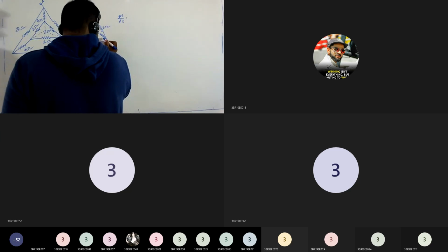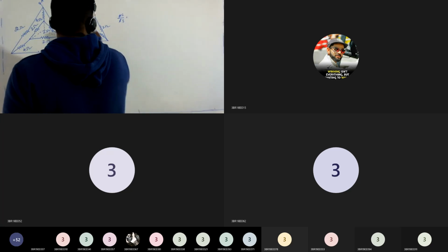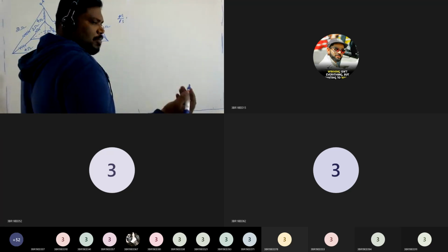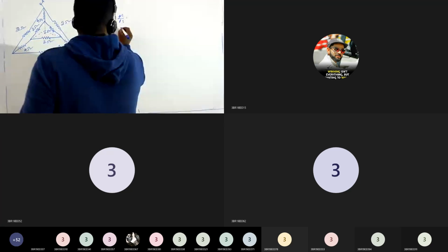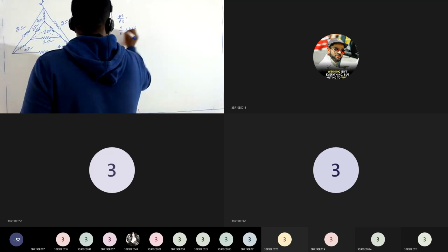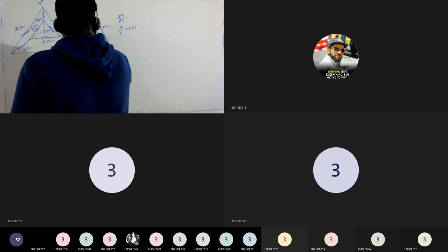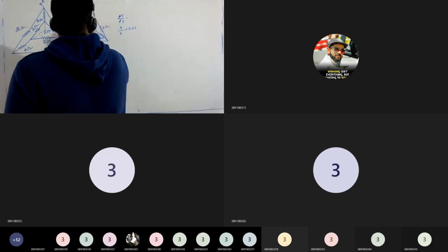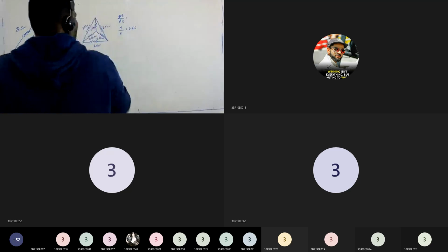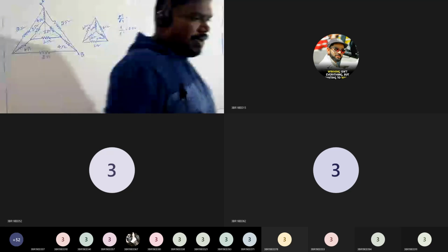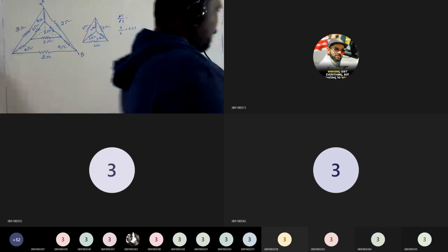Even to calculate this particular wing of the star network, again, product of the side impedances, 2 into 2, divided by the sum, the denominator remains the same. So again I get 4 upon 6, which results in 0.66. So all 3 branches of the star network have the same value, because the delta connected network has equal values.